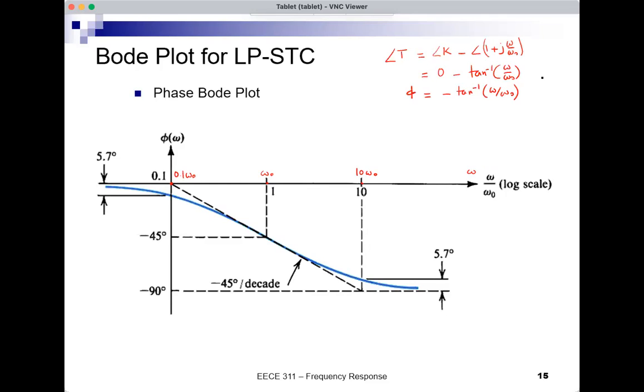And we see that at omega 0, the blue curve goes through this point at minus 45 degrees. These are the low frequencies here, as we go towards low frequencies. Notice that in the log scale, I cannot show 0. Because if I go a decade below 0.1, I will go to 0.01, a decade below that would be 0.001, so 10 to the minus 3, 10 to the minus 4, 10 to the minus 5. I will never see a 0. So low frequency is like our regular minus infinity. This will be DC frequency, so this is very, very low frequency here.